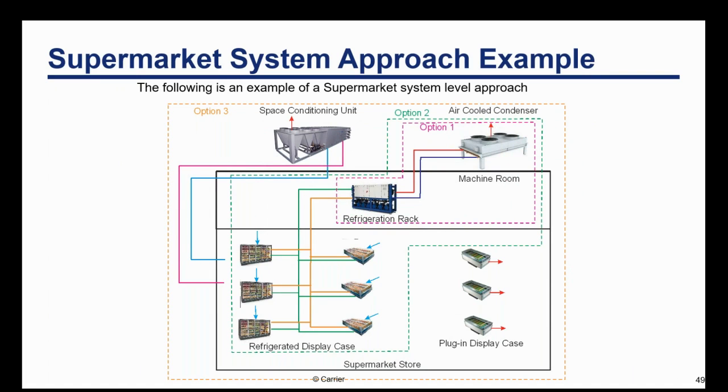And then the last slide I'll show you is a typical supermarket. Supermarket's an interesting thing. We have some metrics in 90.1 on refrigerated racks and walk-in coolers and things like that. But you look at a lot of supermarkets, they may have standalone cases in there. A lot of them reject their heat to the space, and then you put in cooling to cool them down. So there's a lot of work in the industry to say, do we look at the whole supermarket as a system? The same thing can be on the retail. You take a look at a McDonald's that has 40 tons of cooling on the roof. 20 tons of that cooling is to pick up the heat rejection from the refrigeration systems that are rejecting heat into the space. Next slide, please.